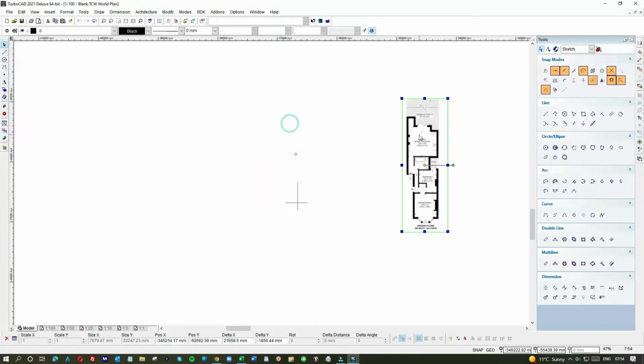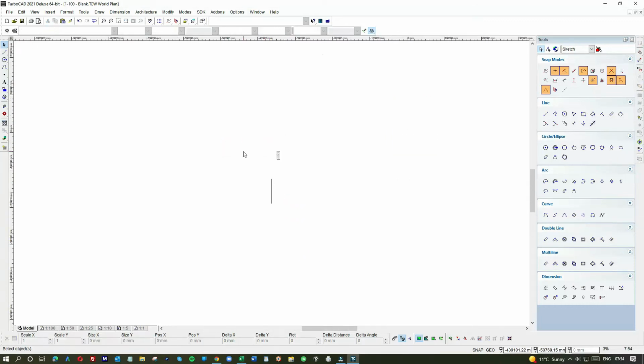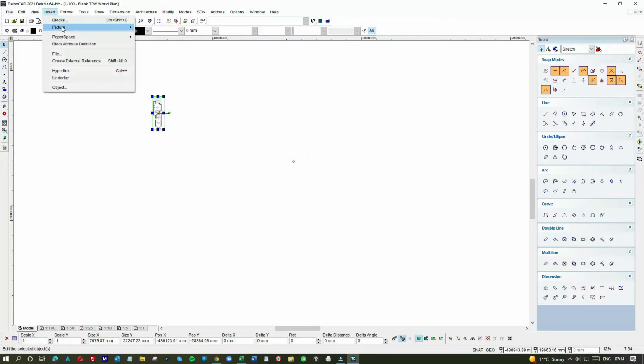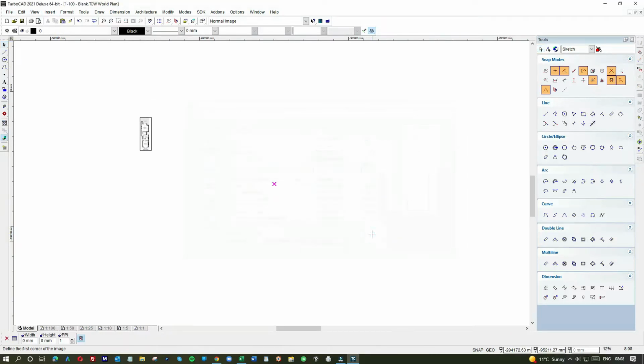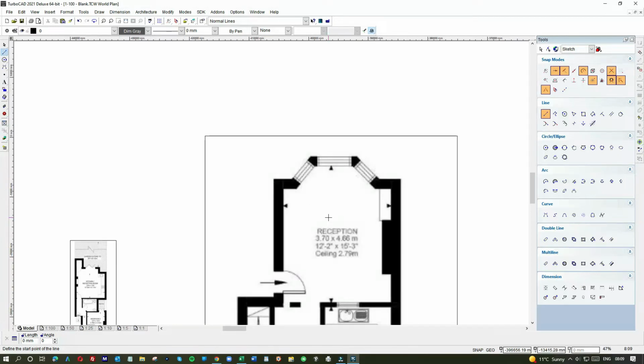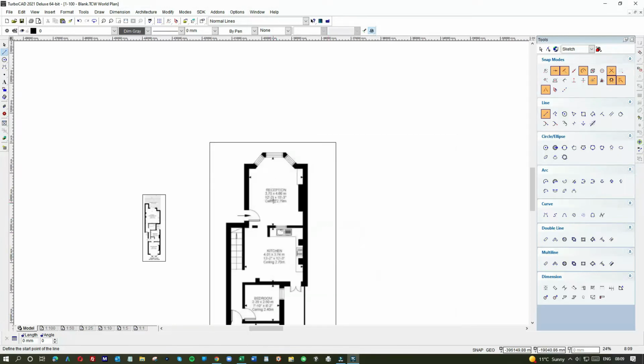So I'm going to clear off all these little lines here, and go over it briefly again. Make it even more interesting, I think I'll insert another picture, from a job I did earlier. Same routine. Click anywhere on the model space, drag down and let it expand. Click again. You've got yourself another PDF or a photograph of a PDF within your model space.